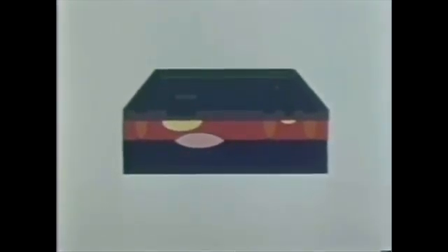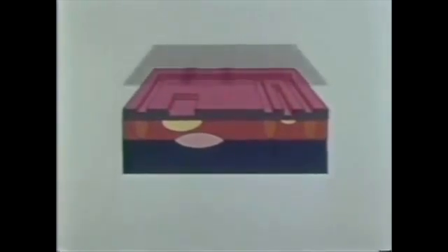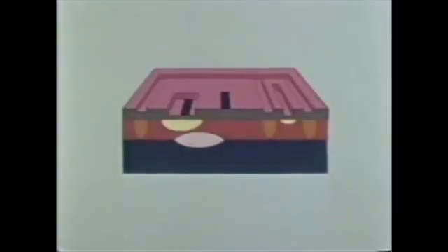Notice that diffusion takes place not only downwards, but also laterally under the oxide. As a result, the junction is formed beneath the passivating layer, where it is protected from the outside world. The next diffusion forms an emitter and a collector contact to complete the transistor. Again, the same process.